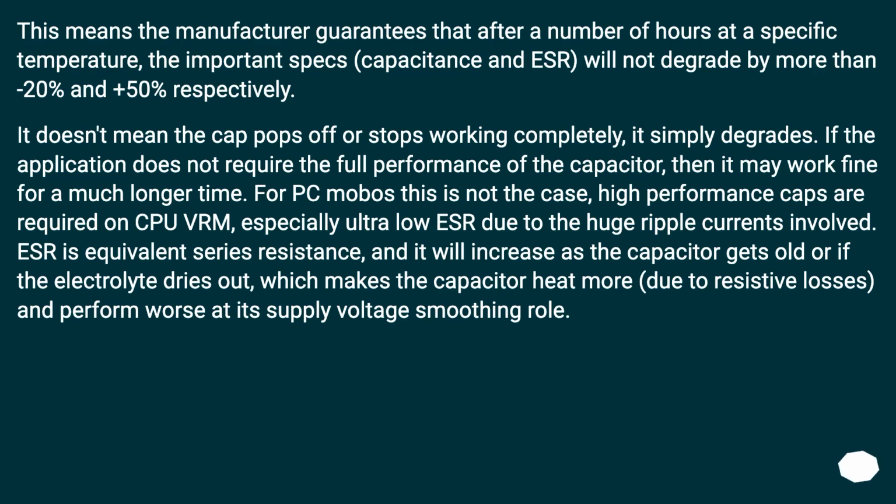This means the manufacturer guarantees that after a number of hours at a specific temperature, the important specs, capacitance and ESR, will not degrade by more than -20% and +50% respectively. It doesn't mean the cap pops off or stops working completely, it simply degrades. If the application does not require the full performance of the capacitor, then it may work fine for a much longer time. For PC mobos this is not the case.